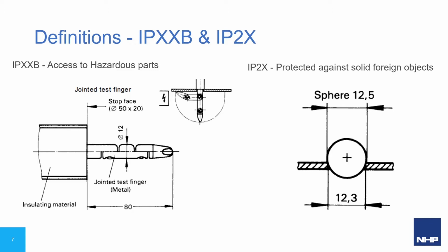As per AS 61439, any barriers must be a minimum of IP2X or IPXXB. This involves two requirements: protected against access of hazardous parts with a finger. The other requirement is protected against solid foreign objects of 12.5 mm in diameter and greater. When we are talking about form ratings, just think if the sections are meant to be separated, ask yourself, when you have access to one section, can you touch the other section with your finger? If yes, then it fails.